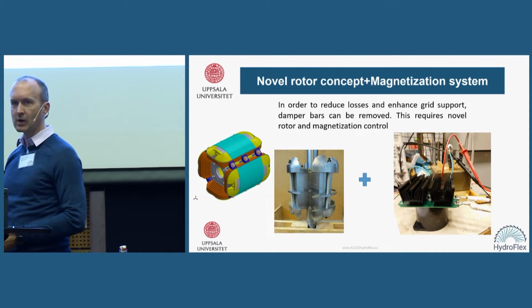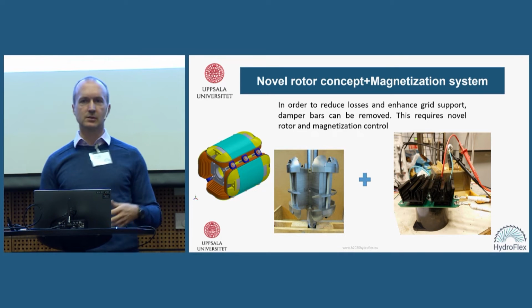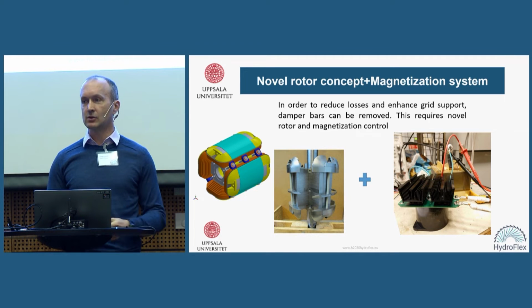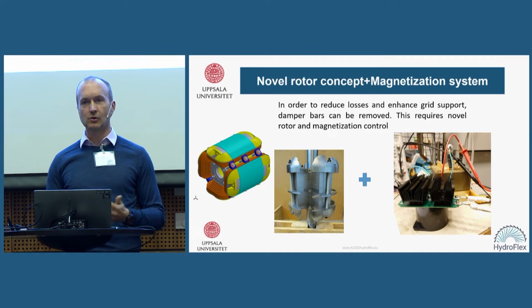And then, of course, we have challenges with communication, challenges with these components. For instance, the black thing you see is a capacitor, and we have to use solid-state capacitors. We can't use electrolytic capacitors if it's spinning with high G-forces and so on. So there are challenges in both the design of the system, but also the components. They have to be able to withstand very high G-forces.